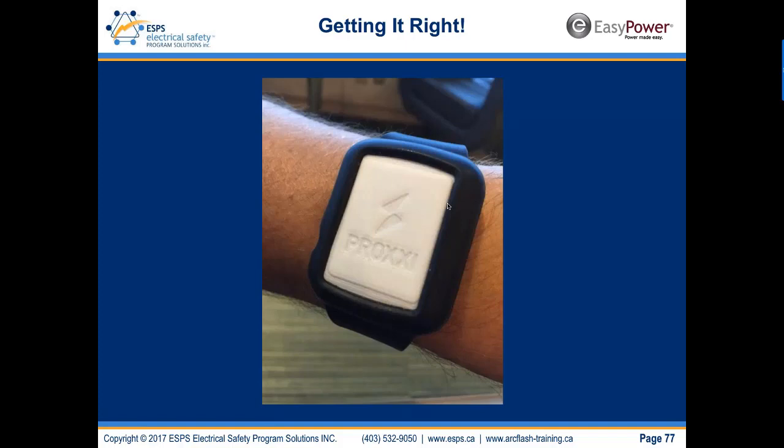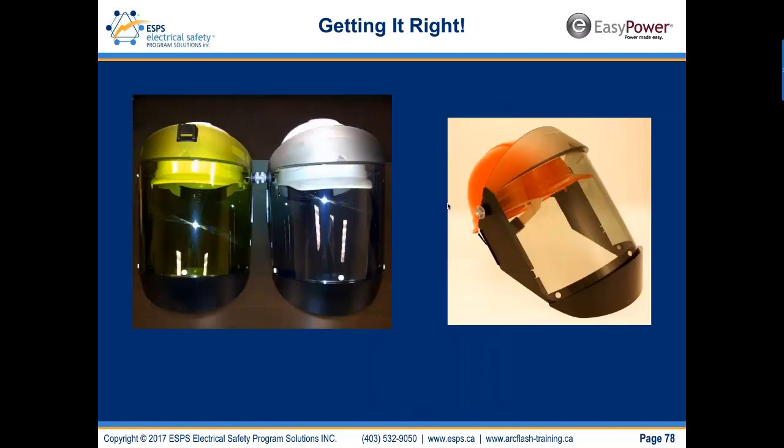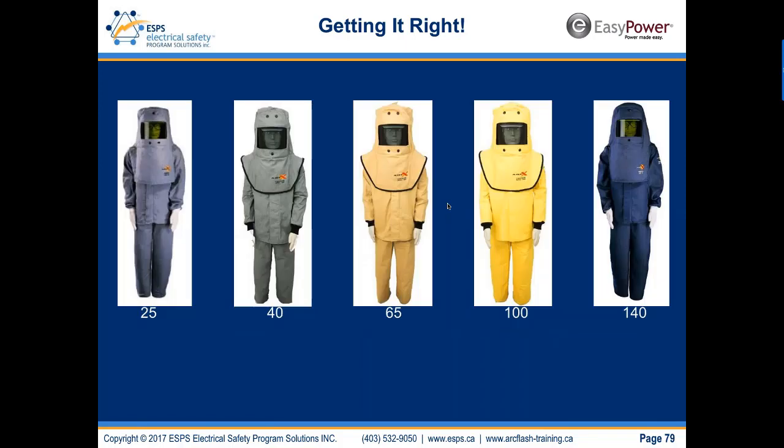This is preventive PPE. And then as far as the arc-rated clothing, there's now true color gray shields, arc-rated face shields, and arc flash suit hoods that don't discolor wiring. This is available from Oberon Company. It is, again, the best for the worker to wear to reduce the risk. The probability of human error is reduced with better PPE where they can see the wire colors as they should.